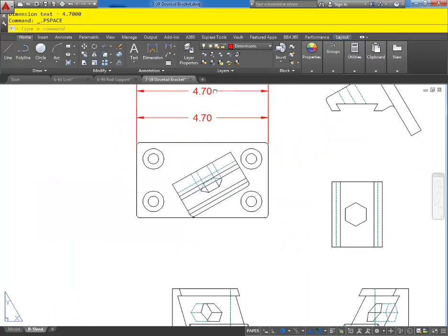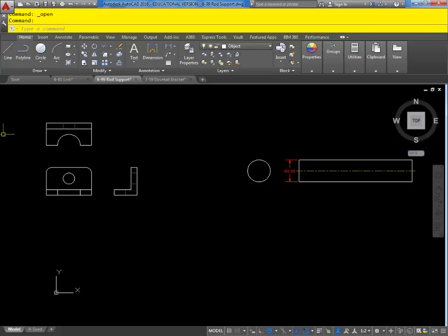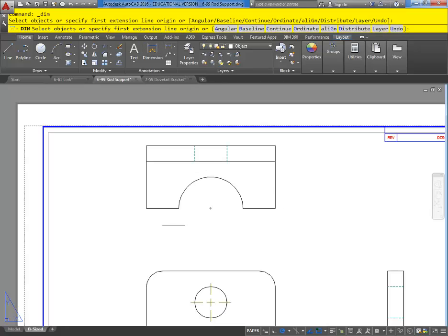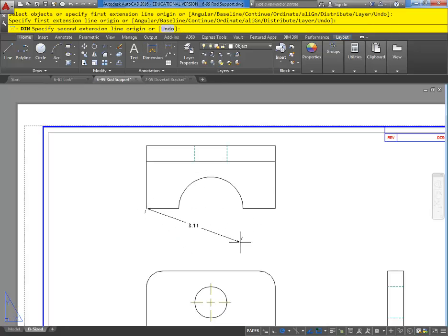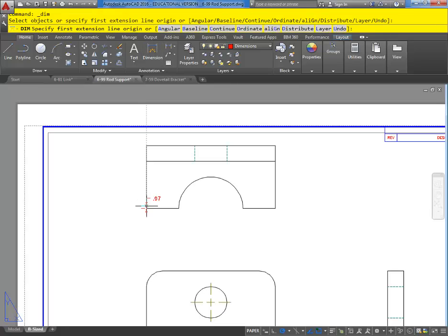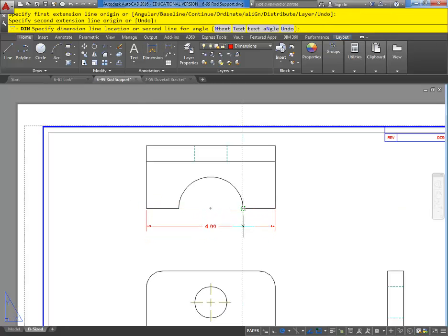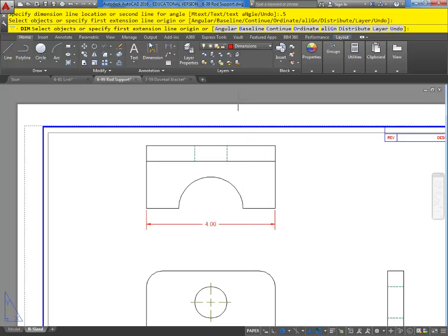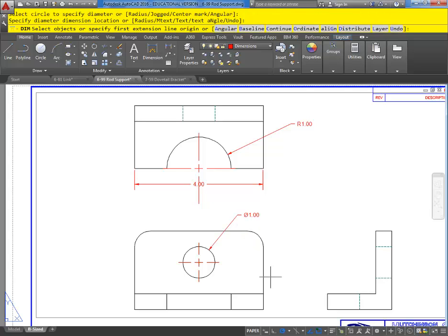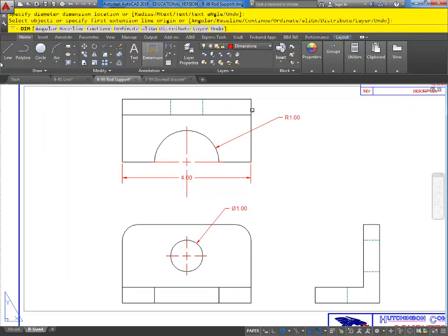And then this fancy new dimension tool, I'll show you a few of the things that it does. B-size, there we go. So this dimension tool, instead of using just the linear one, it works great for creating linear dimensions. You can see it kind of previews a little bit differently. Let me make sure I've got my dimension layer set. So that'll work. I should still be able to track 0.5 off. That all works great. I can use the same dimension tool on an arc, and it recognizes it's an arc and should use a radius dimension. I'll use the same tool on a circle. It recognizes its diameter. So it's a pretty smart little tool. It has some other little tools built into it.